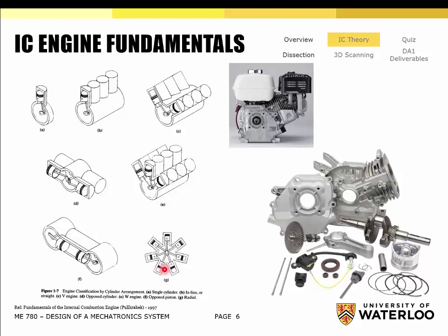Okay, so think about it like this. If the crankshaft, here I'll point with the mouse so everyone can see. Let's say we're looking at this V engine, okay? You want to hook up a propeller, which is the load, to the front of the engine here, okay? It's going to start blowing air, and the fact that you're going to start flying through the air, it's going to have air incoming to it. What's going to happen to these back cylinders here that don't have direct communication with the air? They're going to get kind of blocked by the cylinders in front of them.